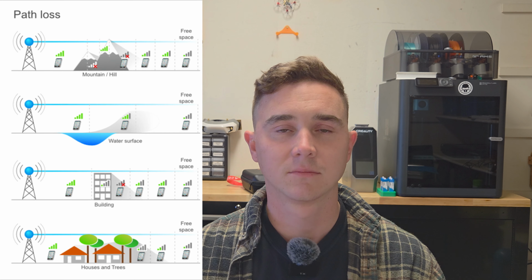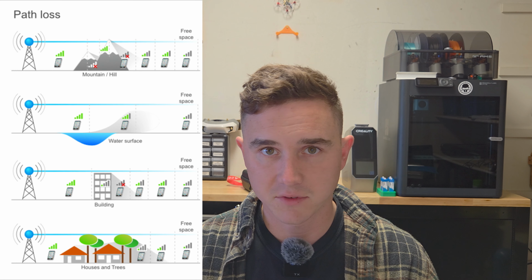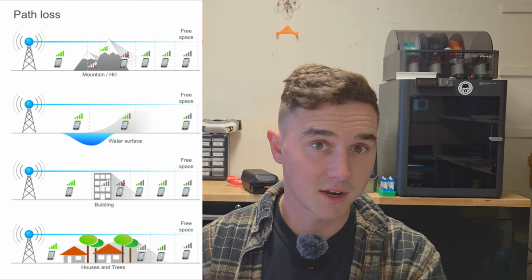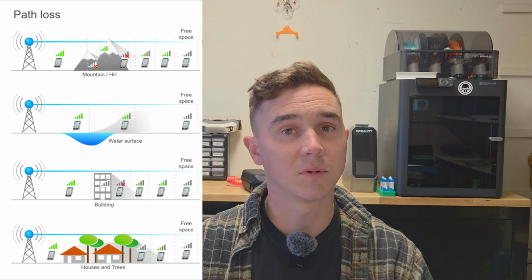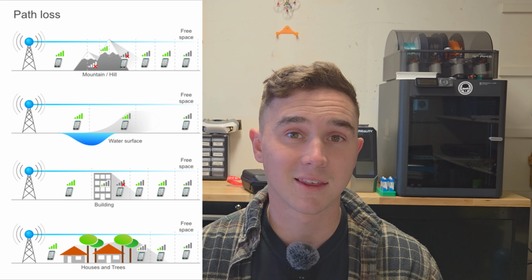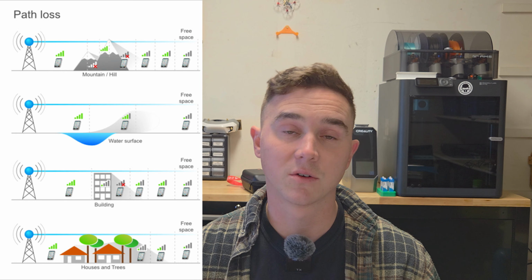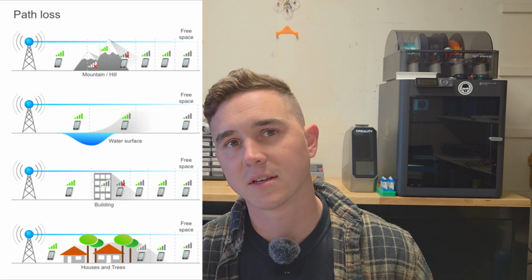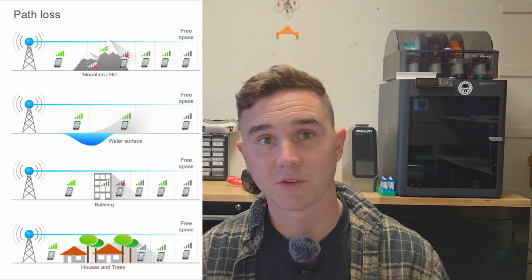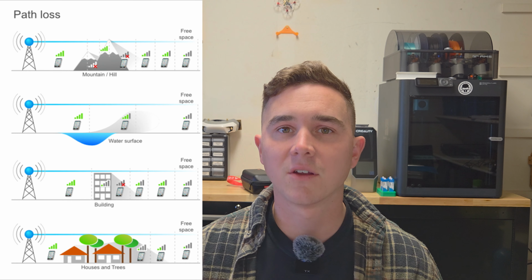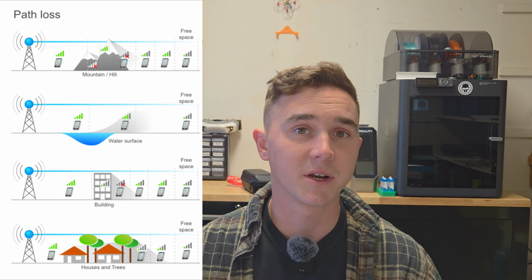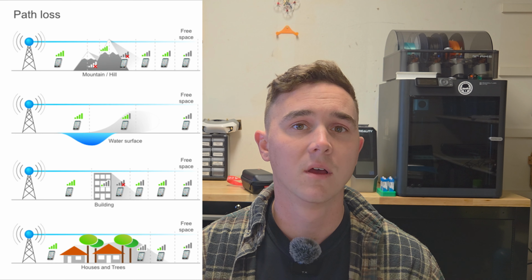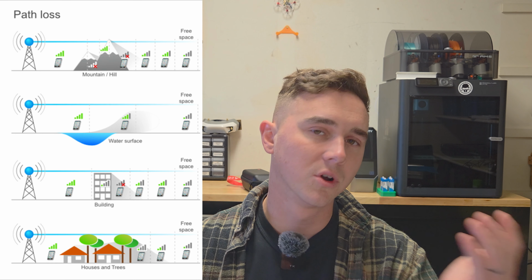So radio propagation, it's basically where the radio waves go. Okay, you can get into the weeds on propagation and propagation theory and stuff, but I just want you to understand things that are going to interfere with your signal. So it's going to be terrain, so mountains, valleys, hills, buildings, specifically concrete. If you're flying in a bando, you're going to lose link probably eventually because those radio signals have to get through all that concrete before either gets to the drone from the controller or to your goggles from the VTX.